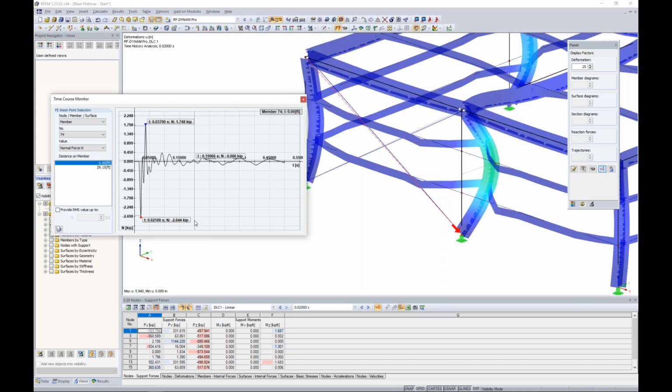So why is this? Well, this is just simply a limitation of the linear solvers. Any non-linear element, so when we're talking tension-only members, are going to be automatically converted into truss elements for the linear analysis. So the program only knows what it knows, and if it sees a truss element internally, it's going to think, okay, well, then it can take on these high compression loads as well. There's nothing stopping it.